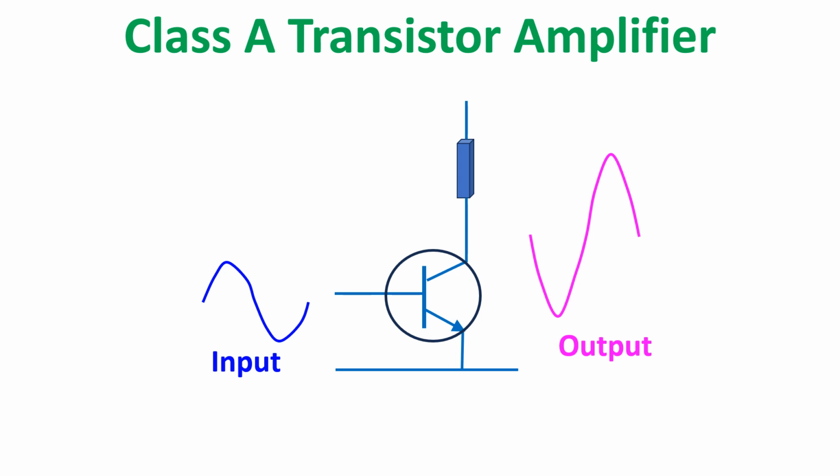Transconductance is the relation between current through the output of the device and the voltage across the input of the device. As the device is always on, there is no turn on time and generally has better high frequency performance and feedback loop stability. Fewer higher order harmonics are generated. Class A amplifiers are best for radio receivers with low signal levels and low distortion.